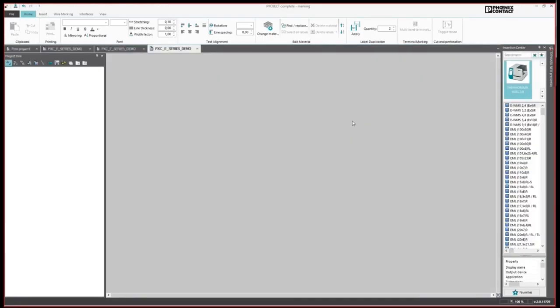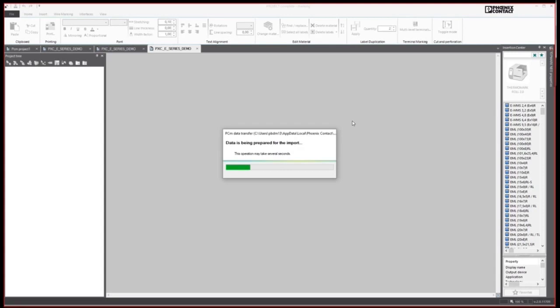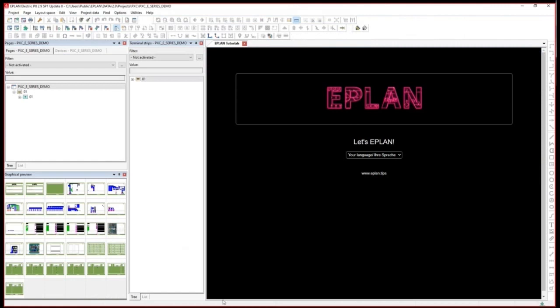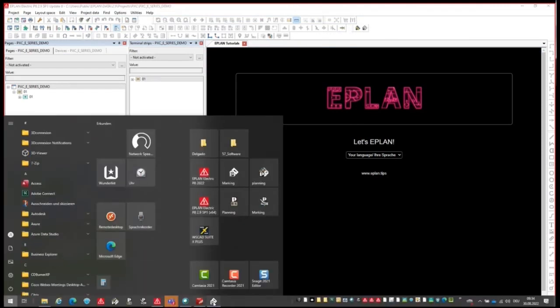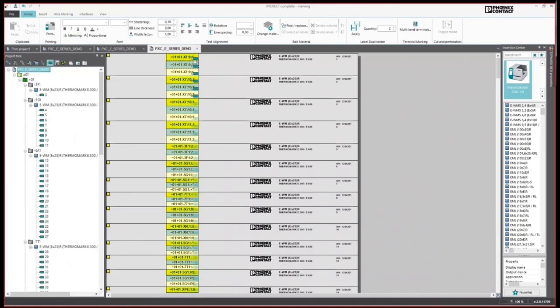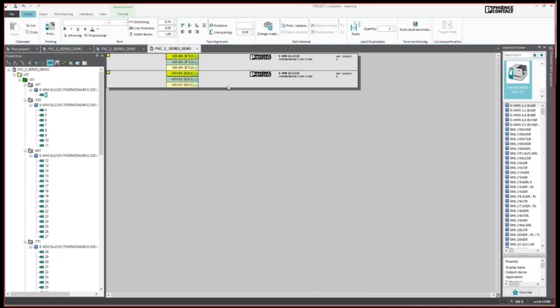You will see later on a video where it is mentioned, but you can see that all information is directly exported from Eplan. And here we have some additional information. In the project tree you can see where this wire is connected on the source side or on the target. Right now the source side is adjusted. You can see that in location higher level 01, location 01 at 3 F1 this wire is connected.